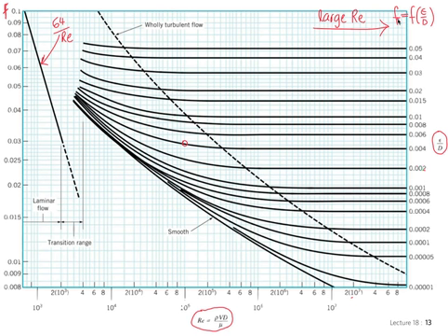If it's very rough, right. Basically the effects of surface roughness penetrate quite a bit, and the whole flow will be affected by it. All the eddies. Remember, turbulent flow is going to be a mixture of different eddies of different sizes, and near the surface they will interact with the surface roughness. And so if those kinks are very large, then that effect is going to be transported all the way through the diameter of the pipe.